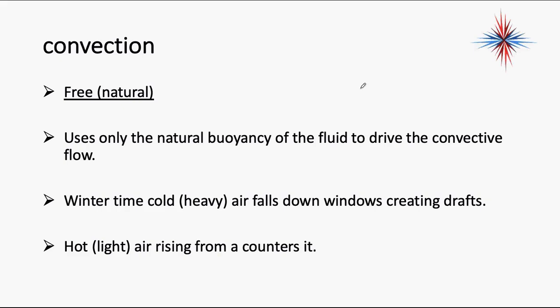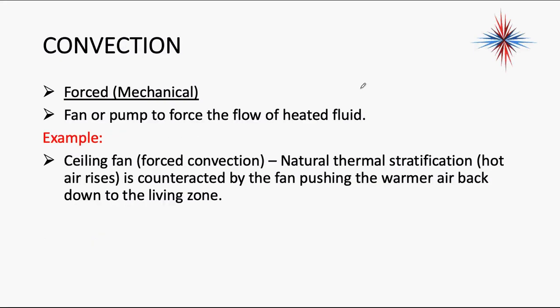Free or natural convection uses what we call the stack effect, the natural buoyancy of fluid to drive the convective flow. In wintertime, cold air falls down windows, creating drafts. Hot air rises. So again, we create patterns within a room using natural convection. Everything we do, we want to counter that natural convection. We use forced or mechanical convection.